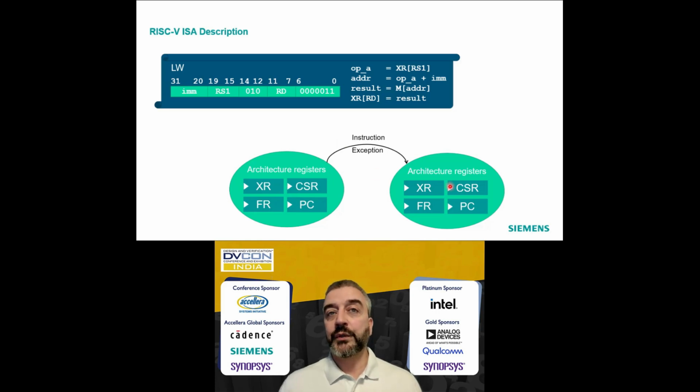And of course, the reverse is also true. I mean, all the other registers are not supposed to get updated. Of course, here stuff like the PC update is often implicitly omitted in these descriptions, but you get the picture. You have a full description of what gets updated and what doesn't get updated. And just as a side note, memory for formal is typically modeled as I/O. So here, essentially, we are not only talking about the update of all the architecture registers, but also the traffic that is produced on the instruction fetch interface or on the data cache interface.